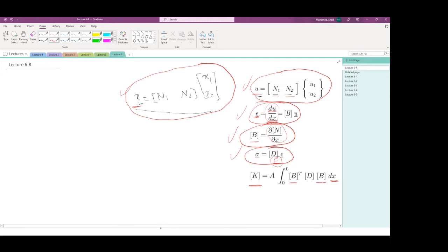So to make the transformation, the stiffness matrix will need to be, I'm just going to rewrite it, integrated between -1 to +1, and we have B transpose multiplied with D, which is simply the elasticity modulus, multiplied with B, and then integrated over xi.